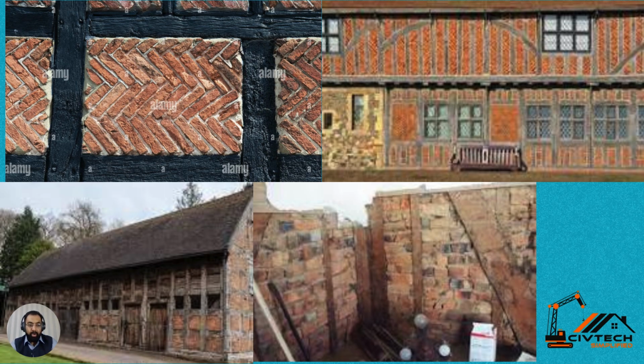Normally it is a zigzag course. So it's basically load is transmitted through that wooden frame, but the filling part is done through the bricks. So this technique is called nogging, brick nogging. It was used in the older era when even the filling was done through stones or through the bricks. But the main thing is the wooden frame.